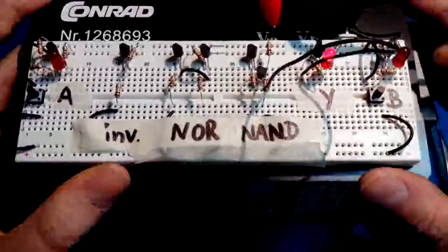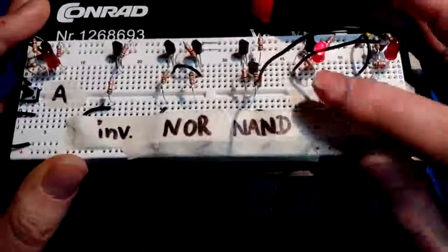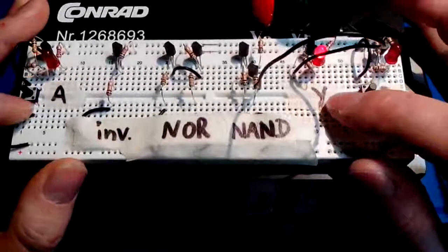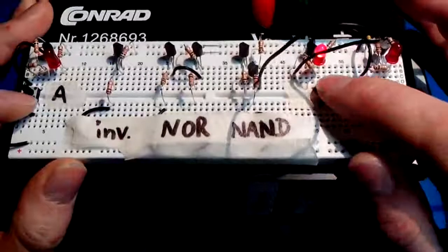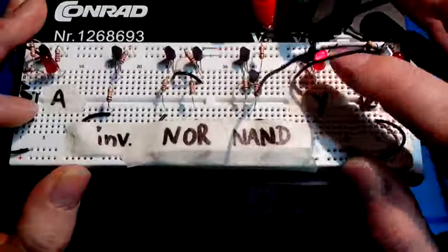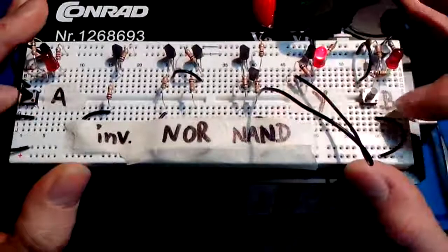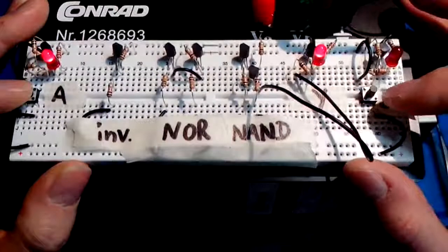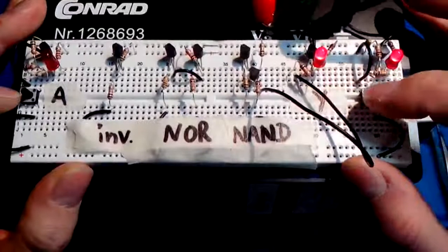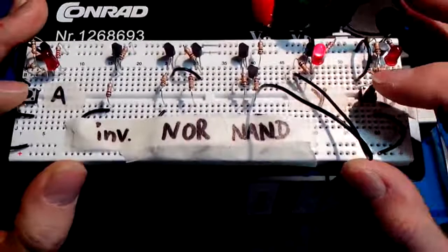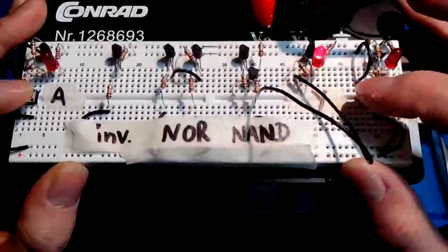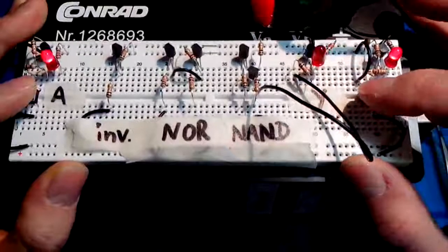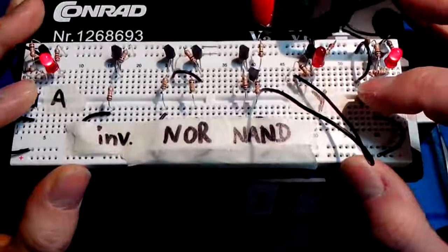Okay, let's look at the NAND gate finally. If neither input A nor B is activated, so A and B are both low, the output of the NAND gate is high, or 1, indicated by the LED right there. If I press A, nothing happens, the output stays high. If I press B, nothing happens, the output stays high. Only if A and B are both pressed, then the output is low, right? So it's basically an AND gate with an inverter behind it. That's the functionality of the NAND gate.